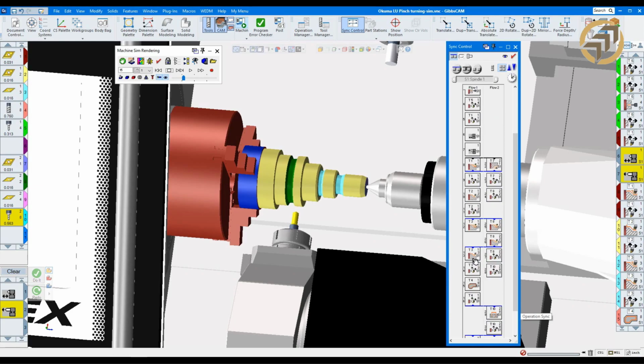And what I have just done, I arbitrarily clicked on some of my operations on the bottom and on the top, and I'm putting another wait code in. So basically I told the system, hey, this operation waits until this operation with the lower turret is finished. And the same again, this operation waits until that turning operation on the upper turret is finished. So sometimes they work together, sometimes I have to make one wait for the other one to be done. Okay, so by that I simply inserted wait codes or sync codes as I think they should be used. Now, with that said, I see all the operations as they are, and I see gaps, and they all have the same size of